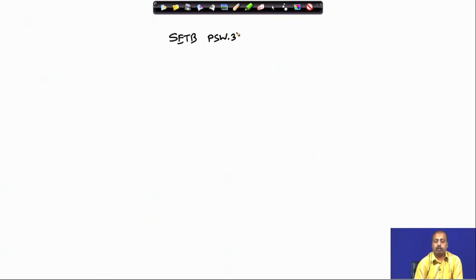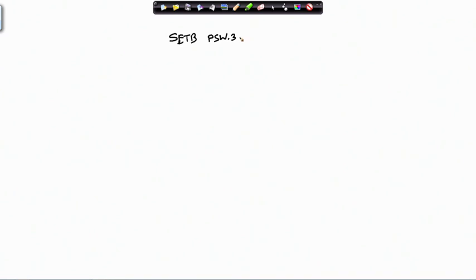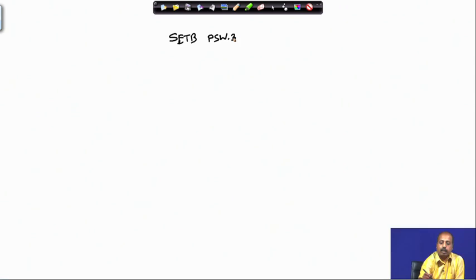So, it sets one of those register bank bits, and it is assumed that by this the register bank is modified. Of course, there is an assumption that this PSW.3 bit was 0 previously. So, the main program was using register bank 00, and that assumption is there. Otherwise, you can manipulate this part so that the appropriate register bank is selected.